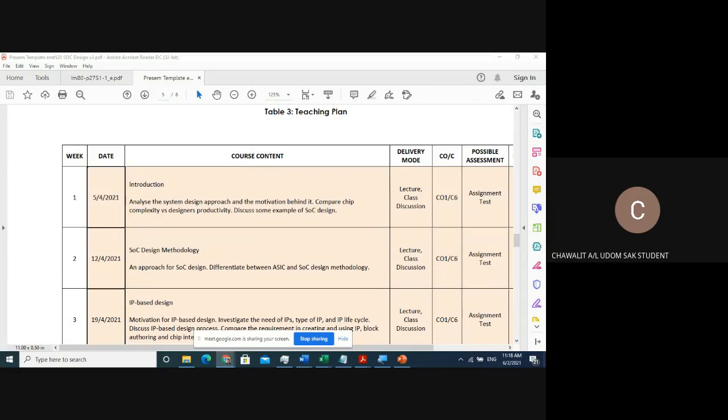But in SoC, mostly the focus is cell-based. Cell-based design includes small-scale integration, memories, system-level module, and mixed signal. Basically, cell-based design uses a standard cell library as the basic building block of a chip. Then the interconnections are routed within the block.